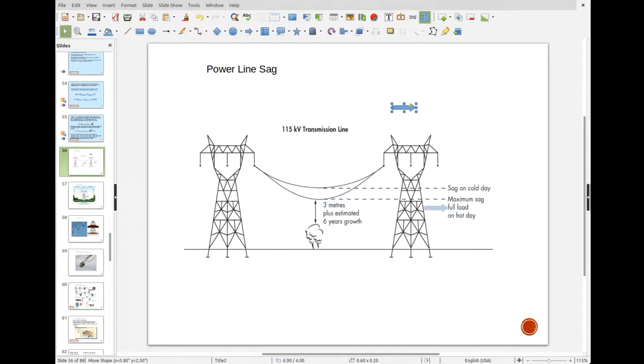And then the other piece, though, is what happens in the summertime when it's really hot. Everybody's running their air conditioners, all right? And those air conditioners draw a lot of current. And so you've got that current flowing through these. And remember that I just talked about that on the other slide, right? I squared R. The current is heating up the wire.